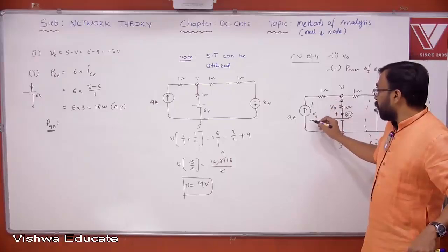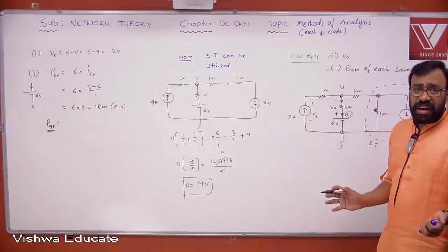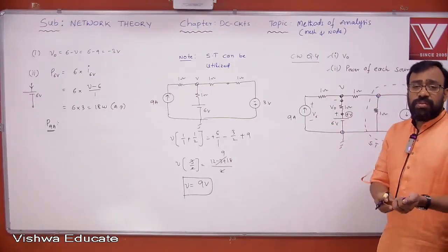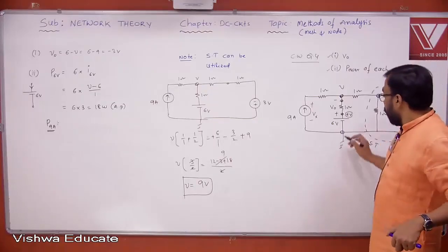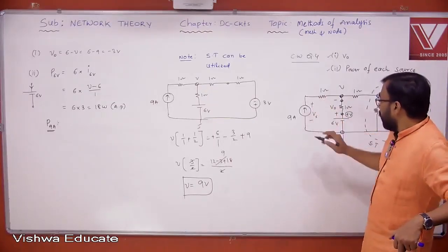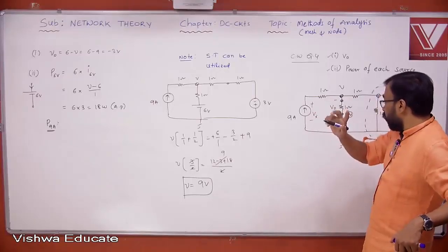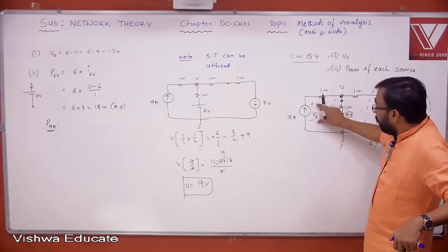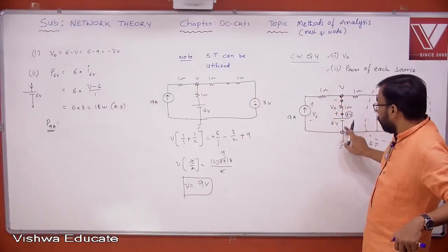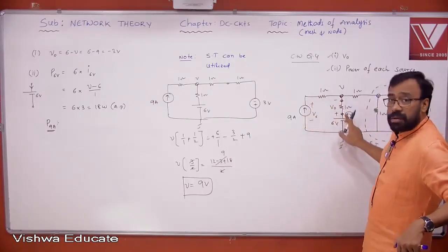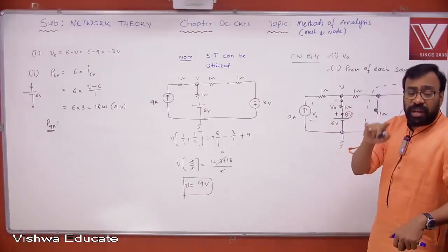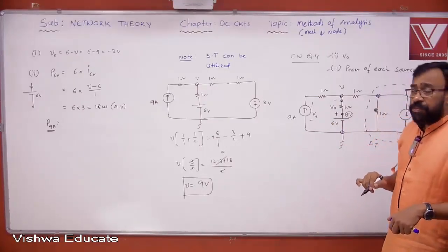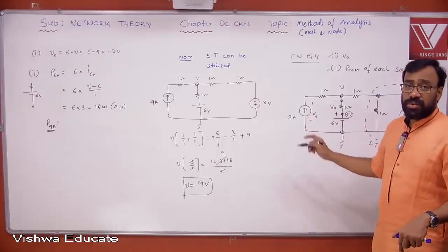Sir, how did you get the plus minus polarities here? I'm just taking them randomly. Let me see whether it comes out as a positive value or a negative value. It doesn't matter. Now, if this is 0, I'll explain you two procedures here. You can apply KVL or the touching concept to get this value, plus to minus like this. Assume some voltage Vx. I think we did the same procedure in mesh analysis, where I determined the voltage across the current source in one problem.